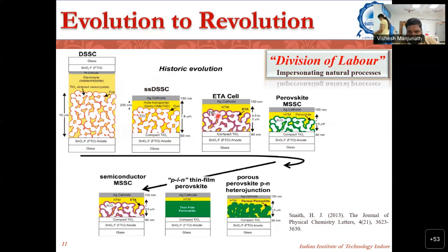Similarly, TiO2, then they sensitized. Here it was sensitized, here it was a proper confined coating, right? And then the perovskite mesoporous structures. So here TiO2 is an N-type semiconductor, whereas here they used again Al2O3, which is an insulator. And this was possible because perovskite itself can absorb light, and it can dissociate electrons by itself, and allow them to be collected at the load.